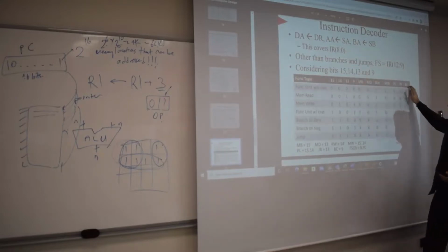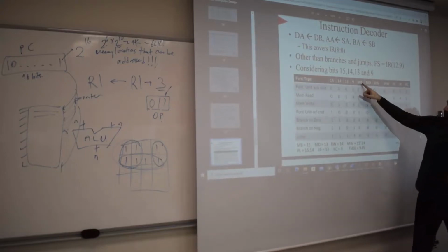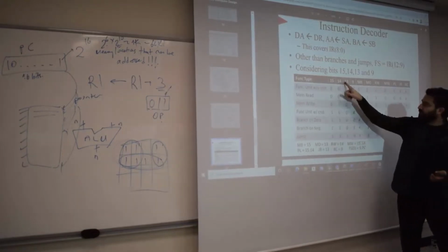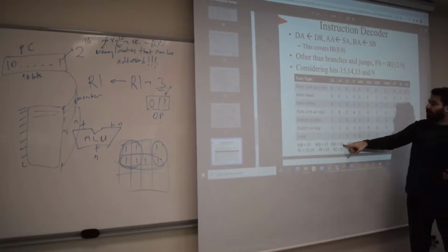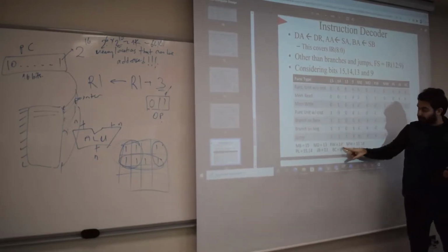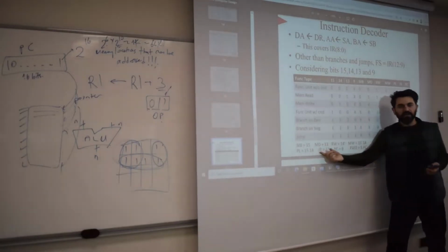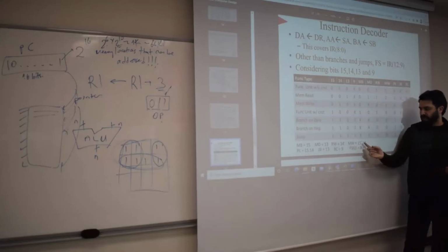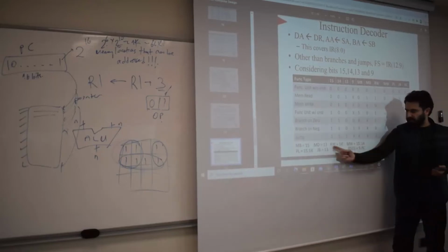But the rest of them is just 16 bits. And based on that, MB, for example, turns out to be the 15th bit. MD turns out to be 13 bits of the instruction. RW turns out to be 14 bits complemented. Okay, MW similarly can be found, but those are just simple Boolean expressions. Okay, you see an AND operation and negated 15 ANDed with 14, etc., etc.